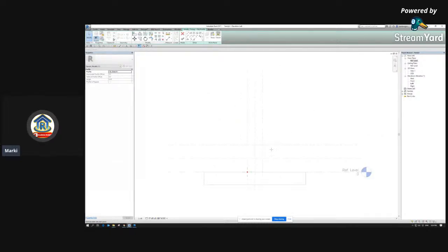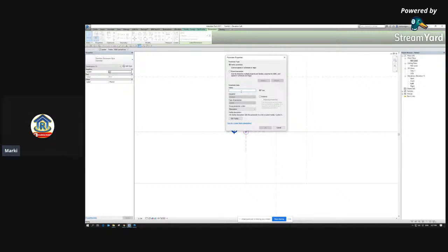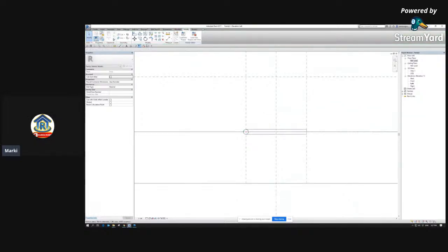I'll go to my left side elevation and then I'll sketch according to the center. I'll make this parametric. To make a circle parametric, you enable the center mark visible and then lock it to a reference plane, X and Y, and then put a diameter, then make a parameter. I don't know why my family is working slower right now when adding the parameter, but I hope you can bear with me. There. I'll just name it Diameter. Then finish, finish. There you go.